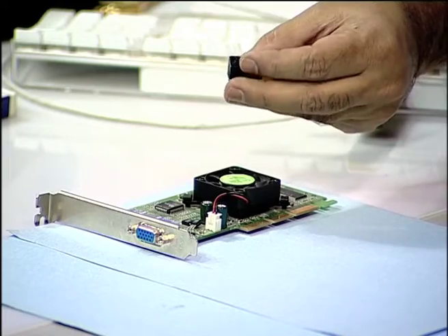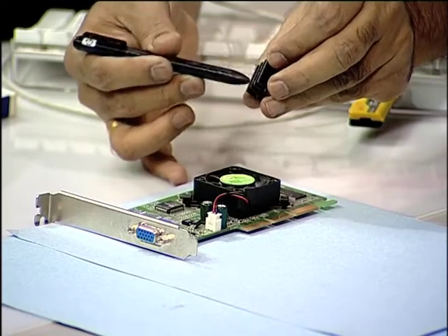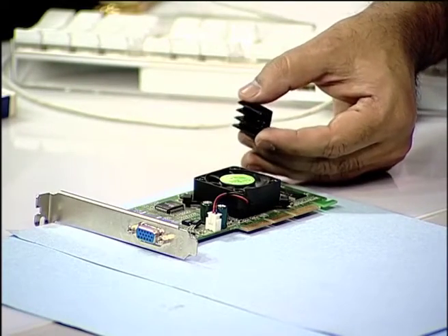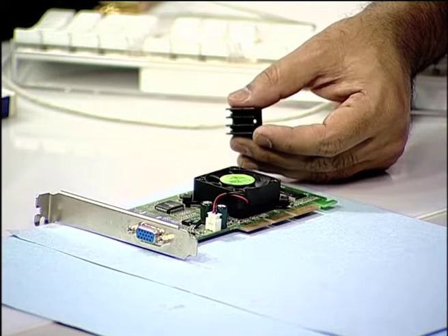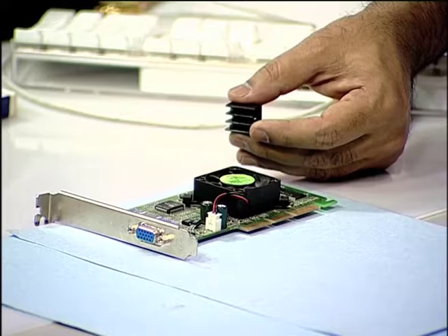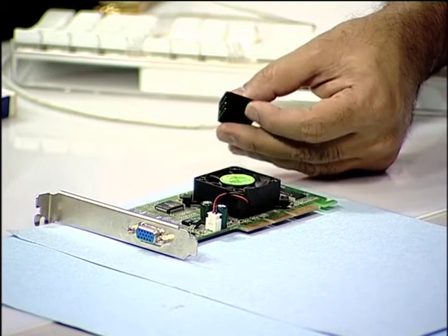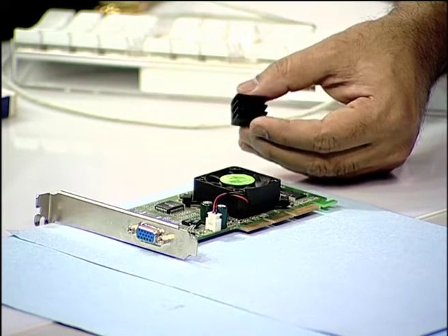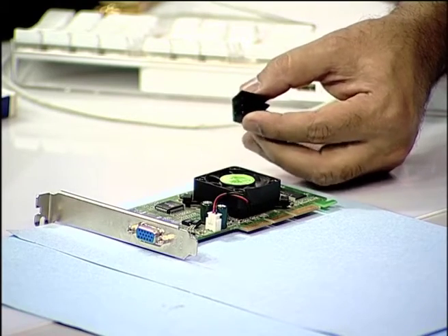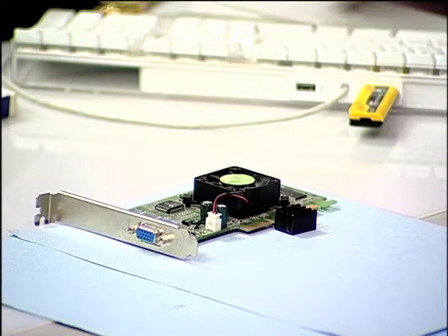So, this material of heat sink is an aluminum material and you can see this is lightweight and this is coated black. Okay, and you can see the special corrugated structures here, and these structures are provided basically to provide more surface area, and more surface area means more heat can be removed from the active device. And for effective cooling, this is black anodized aluminum. Okay. So, these are an entire set of technologies that are available today, which a designer should be aware of.